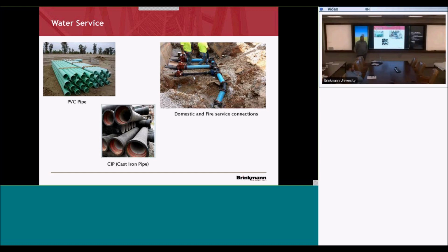So if it's irrigation, well, that water is not getting drained down there, so you shouldn't get charged for it. Now MSD is allowing us to do two meters, to save the owner some money through maintenance. The other trick is a sub-meter inside a mechanical room. Then you can deduct the sub-meter off.